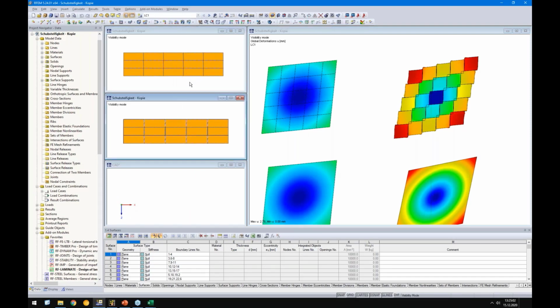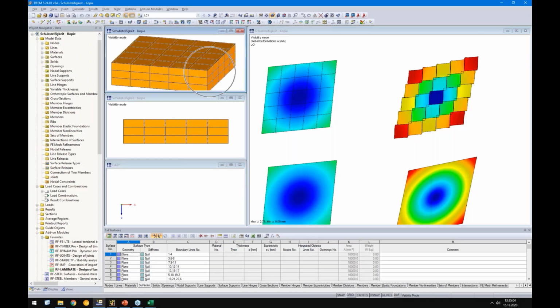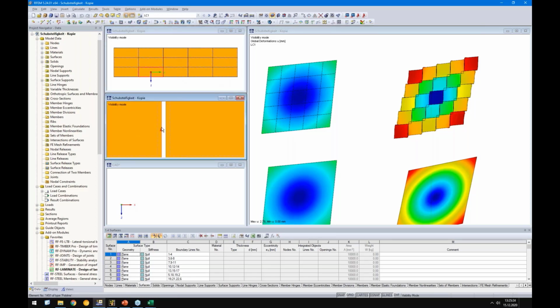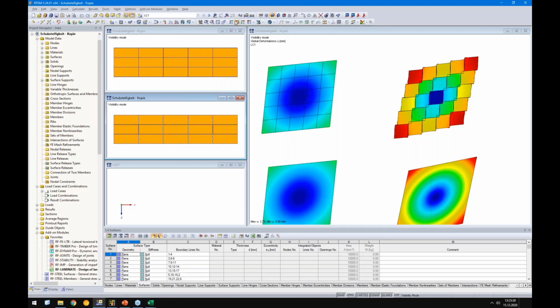All right, so here I have prepared a small example, and these are solid elements. And in the upper one, I have glue on the narrow side, so it means there is a rigid connection between the solids. And on the bottom side, you see I have modeled a small gap in between each board, from this direction, and also in the other direction here on the upper side.